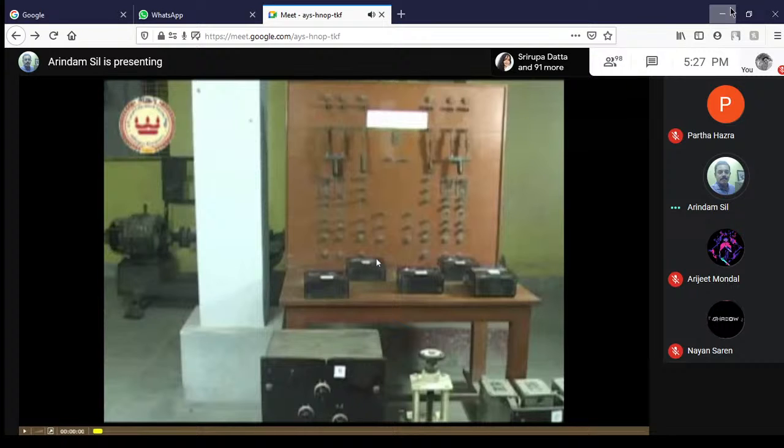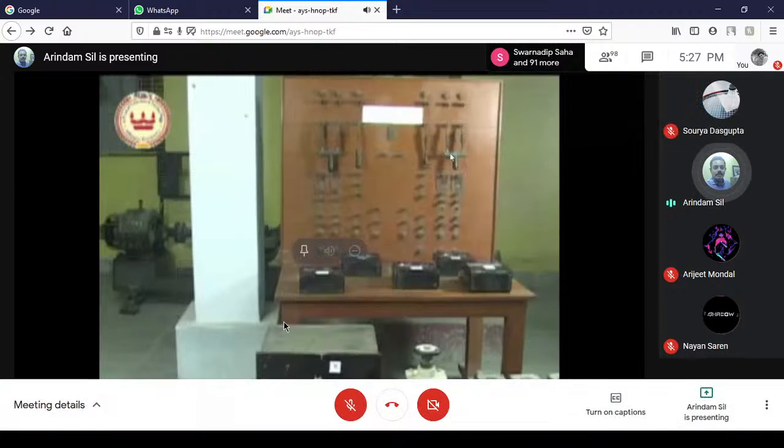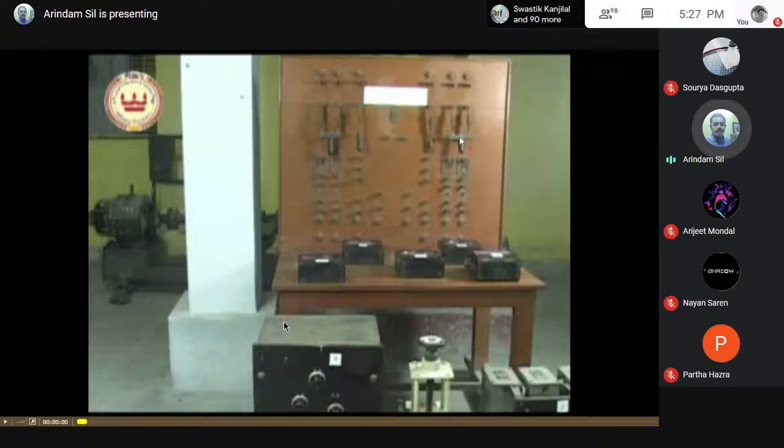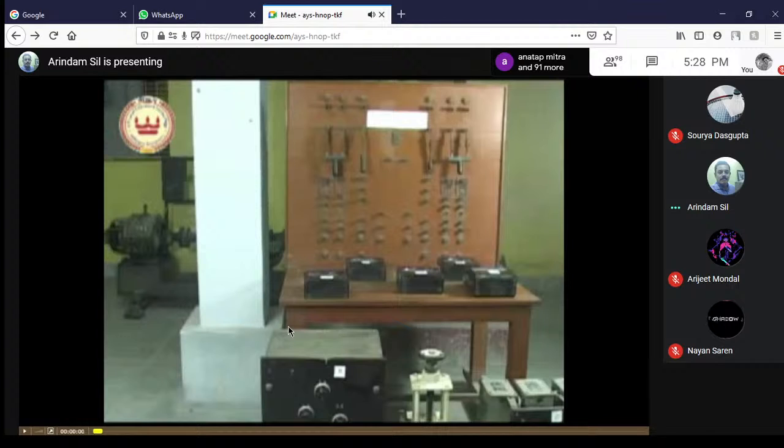This particular is a switch, which is a double pole, single throw switch. Means what? If you put it up, it will go to these two connectors and it will get connected out there. So the power is connected here actually. It is connected through these two metal connectors and it will go through this and it will come out here. These 1, 2, 3, 4 comprise fuse wires. If anything goes wrong in the table, the fuse will blow off. Am I clear?